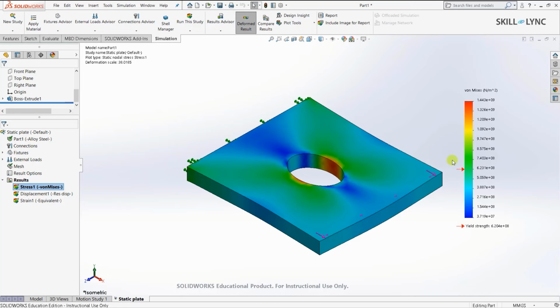So what happened here is that since we are using a linear analysis, the results are valid up to the yield point of the material. The arrow mark shows the point at which the yield strength of the material was exceeded, and thus all the results above the mark are not acceptable. We will have to run a non-linear analysis to get realistic values from the simulation. So since we are performing a static linear analysis and the stress values which we had yielded are much higher than the yield strength value, then we should be switching to a non-linear analysis to get reliable results.